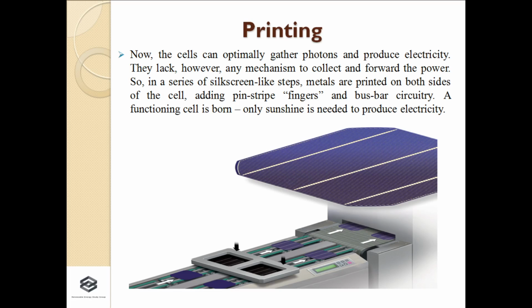Generally, the silicon wafer or silicon cell is made from basic silicon material. This silicon material is kept in a quartz crucible at a higher temperature, and boron impurity, a P type impurity, is added. After this doping, we get the solid bar of silicon by dipping a wire frame inside this molten silicon. Once we have this bar of silicon, we cut it into 2 feet lengths, and it is sliced into wafers of 200 up to 500 micrometer thickness. Again this wafer is etched with a surface texturing.